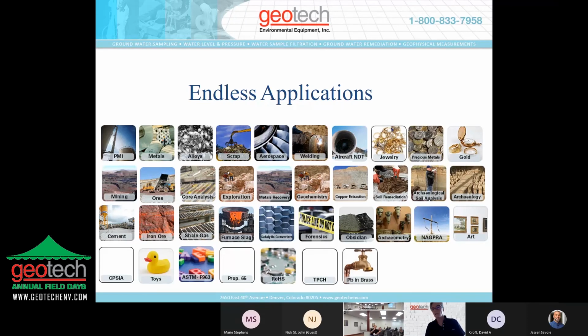So they mandated 590A, which mandates that every in-process piping in any utilities, refinery, or any type of plant that pushes material through processes like this has to have 100% PMI, positive materials identification, which means you identify what materials are in place so that they won't degrade and you won't end up with an explosion like that. Because when you're pushing all these chemicals through a pipe, you can end up with an explosion if it degrades the material and catches fire, and lives can be lost.